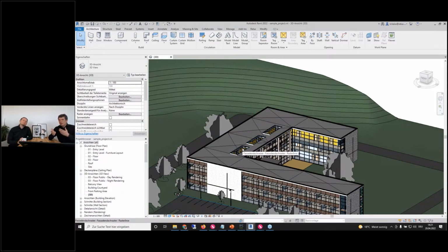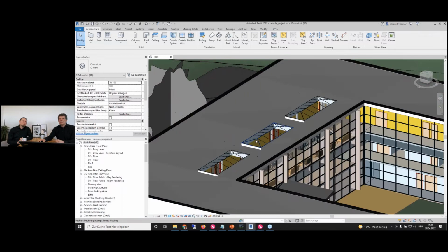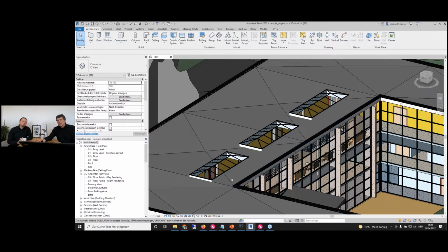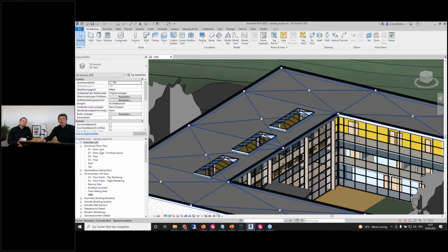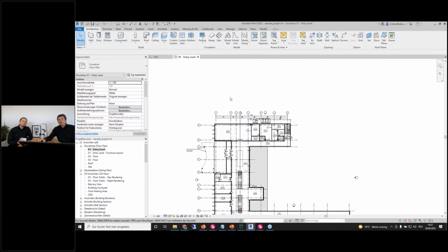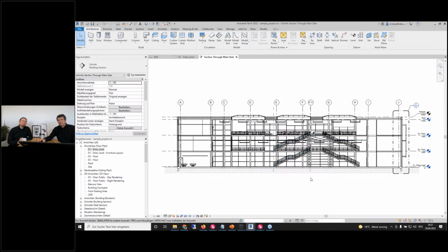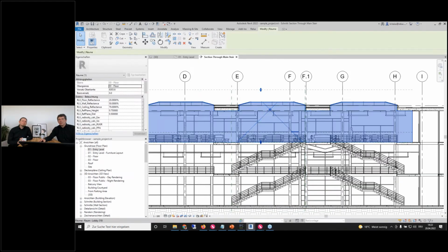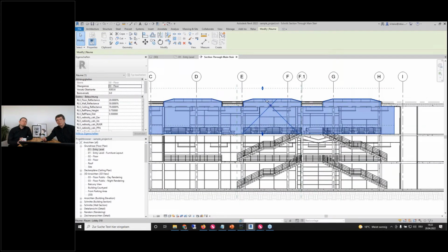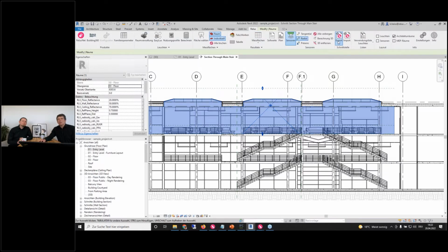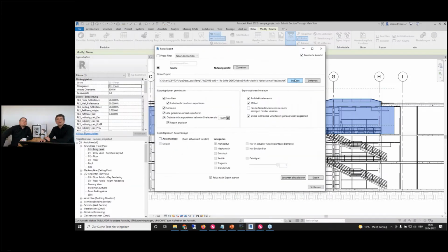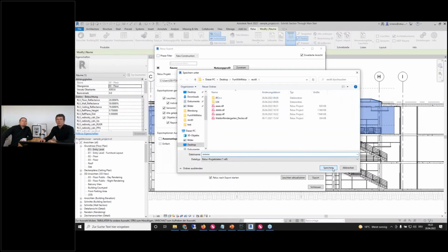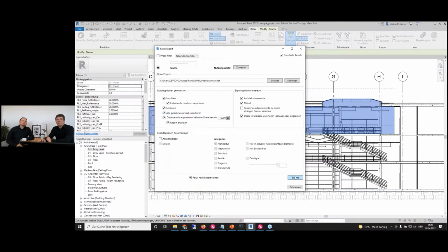But now we are working together with Revit, and we have found a solution to realize this also for more complex room forms. This is an example from Revit, where we have a complex skylight situation. I will jump here into a section view, and select this upper room with this complex roof. And now I go to RELUX and go to the export function. You have to name the project file. Create a project file for this room and export it to RELUX Desktop.